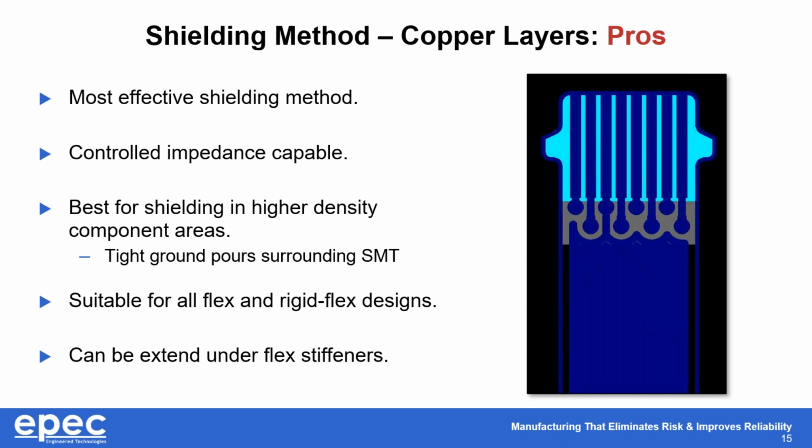Suitable for every single type of design out there. You can use it in all types of flex circuits and all types of rigid flex designs. And it can be extended under flex stiffeners, and that's something that I'll delve into a little bit more once we get to the pros and cons of shielding films.